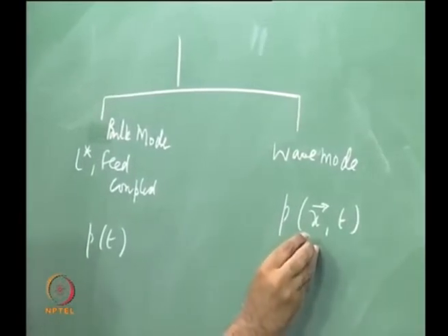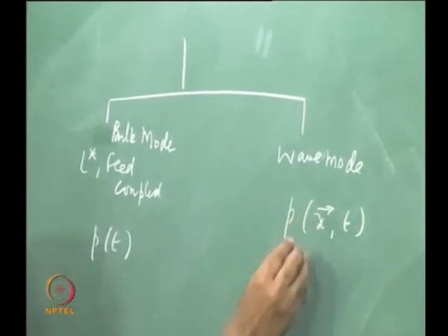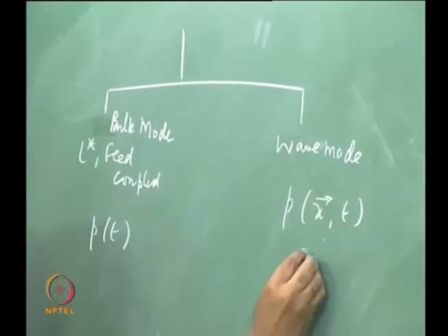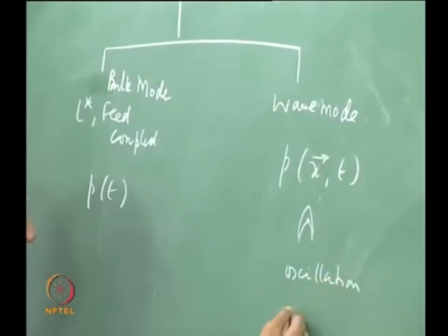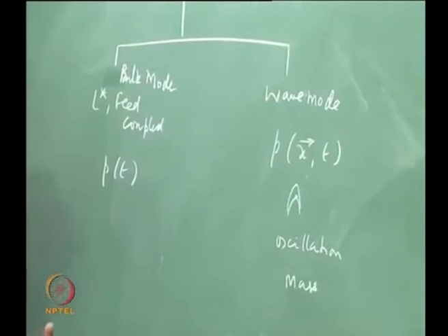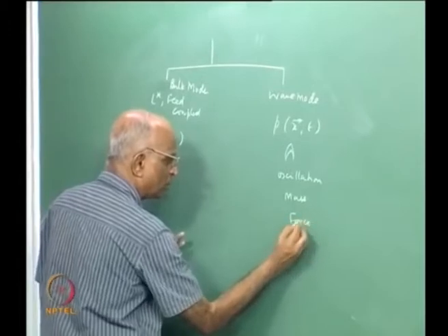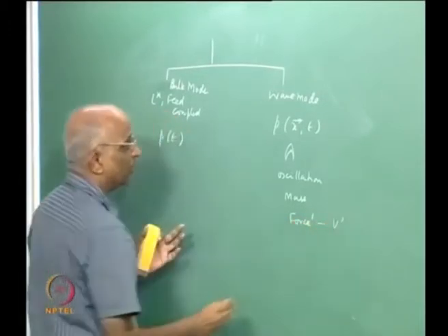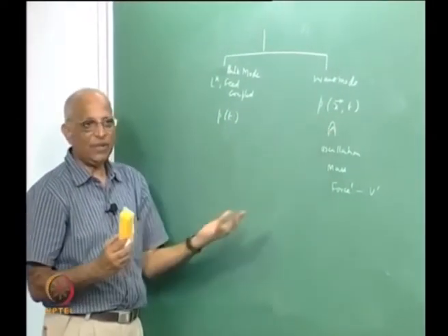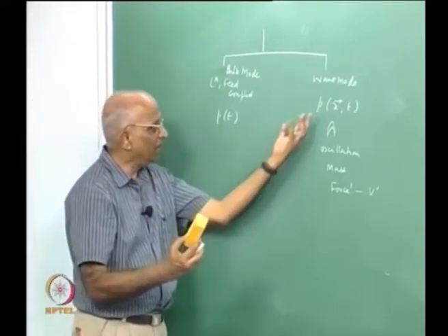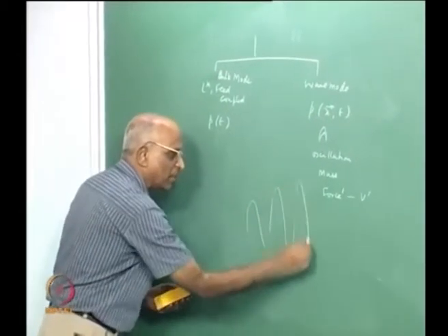If heat release is at the same frequency, and because it is unsteady heat release, at the point of maximum pressure perturbation, you add heat, well, I get an oscillation. It need not be from heat alone, it could be from mass addition also in phase with a pressure perturbation, or it could also happen with a body force perturbation in conjunction with a velocity perturbation. And now we know why combustion instability has to occur. Energy is being supplied by the combustion process, and it drives the oscillatory pressure. In some cases the pressure perturbations keep on increasing.